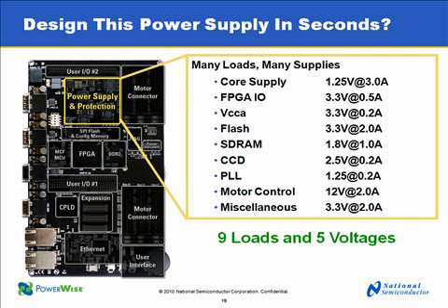This particular example is a board that was designed at National Semiconductor around an FPGA. It's got a core supply, some IOs, a VCCA, flash, SDRAM, a CCD load, a PLL load, motor control, and miscellaneous load. So this breaks down into 9 different loads and requires 5 different voltages.